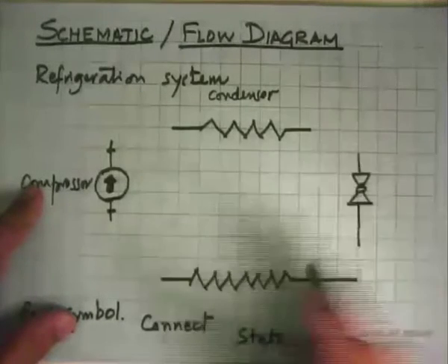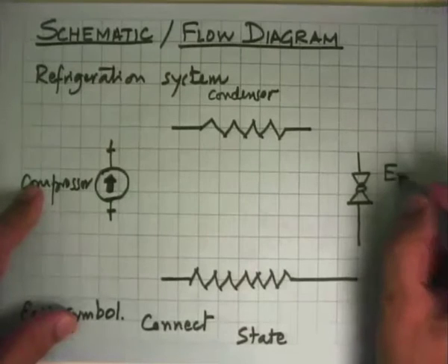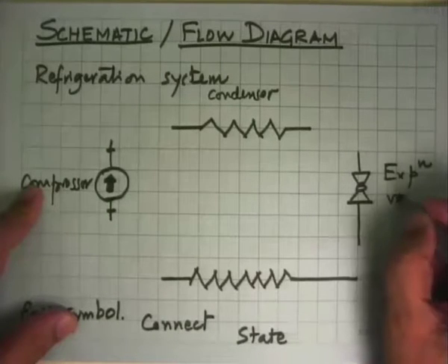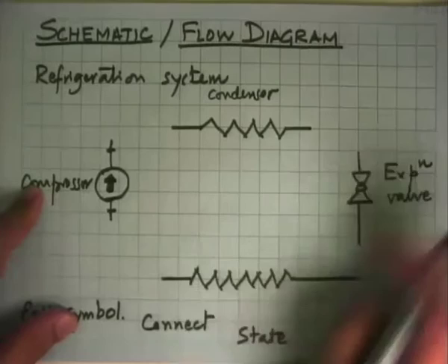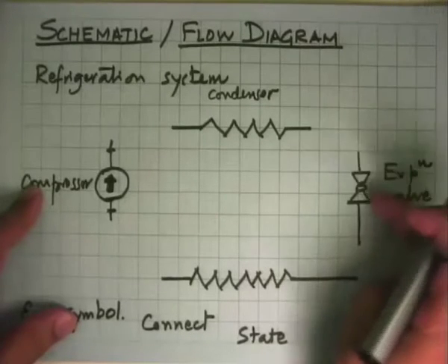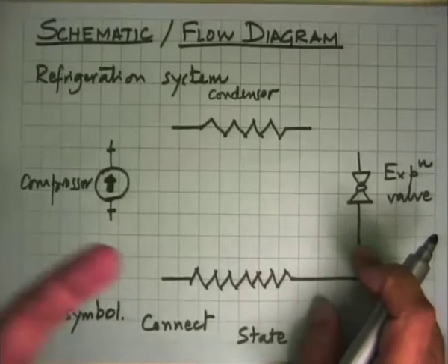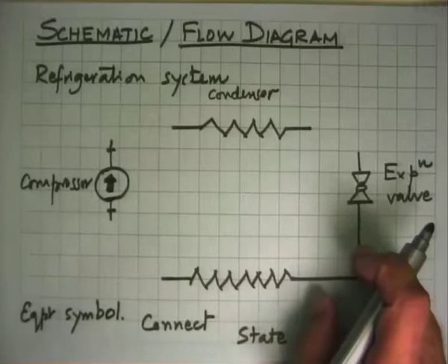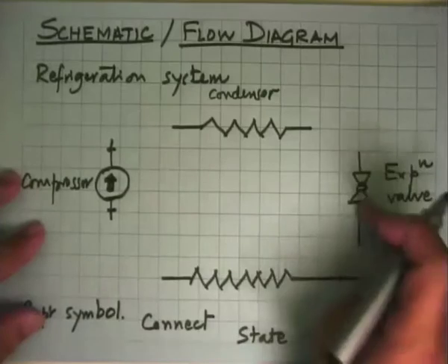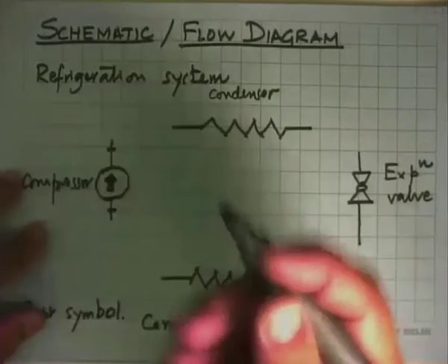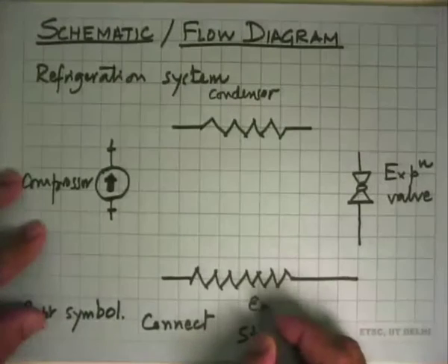The third device is the expansion valve, where the saturated or subcooled liquid goes in, throttles, changes phase, and the temperature drops. And it is this drop in temperature and the cold fluid that we get, which we send into the evaporator.